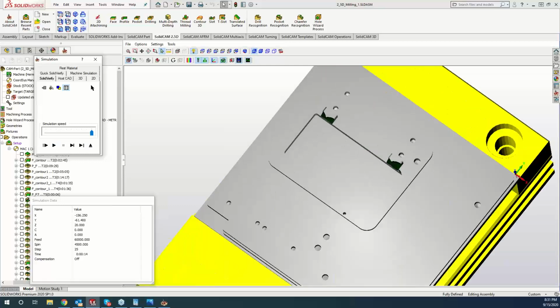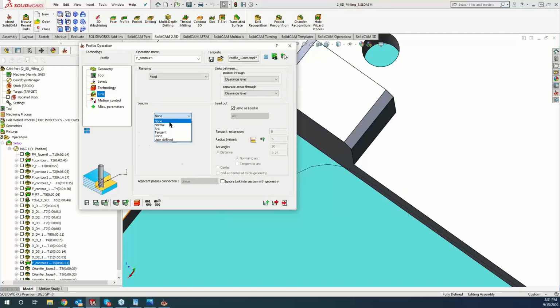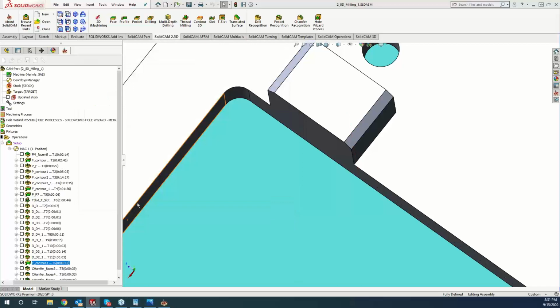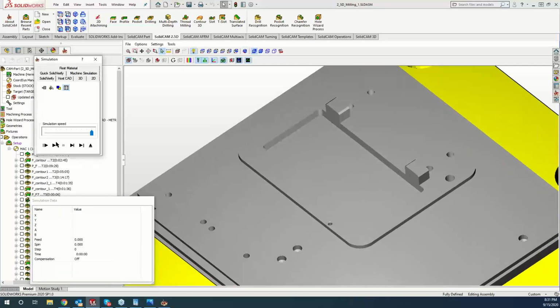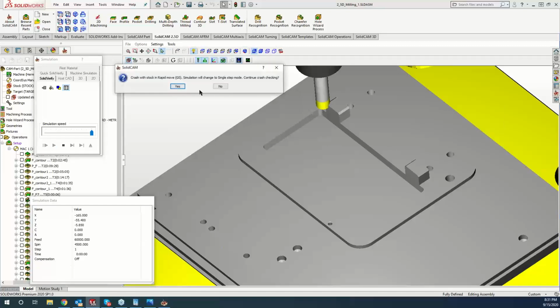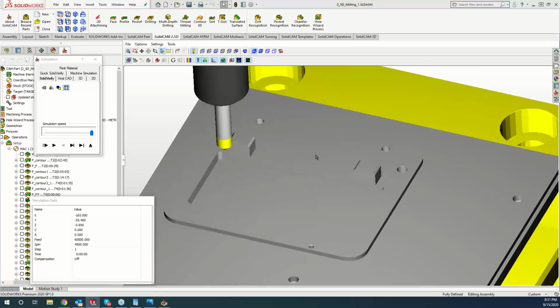Yeah. Yep. And then, I think the moral of the story for everybody watching at home is to embrace the power of the chamfer recognition. As you can see, it's definitely a lot more labor intensive here to try to get stuff. Yeah, see, I'm still crashing in there. So I'm going to have to keep going back and forth and playing with that, reducing that extension to keep getting it small so I'm not coming straight down on my part and wrecking our part.